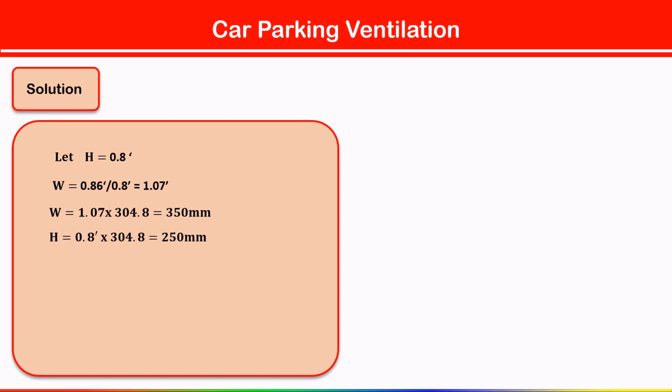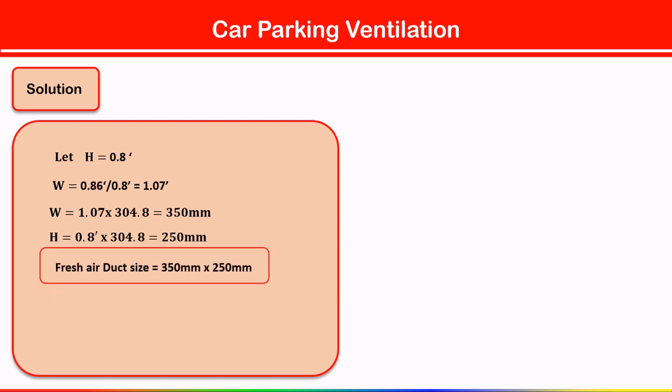In this way you have to do the calculation. Same way, finally we get the fresh air duct size. Not exhaust air here, remember, here we get the fresh air duct size 350 into 250 mm.